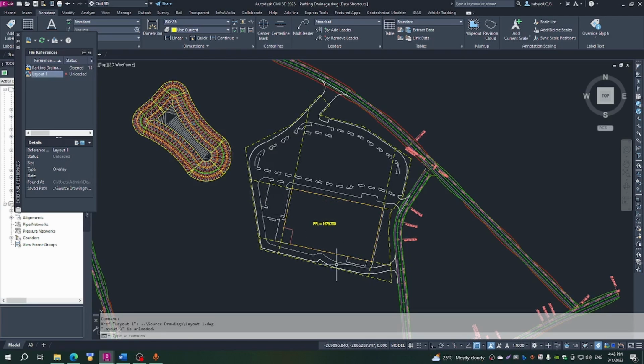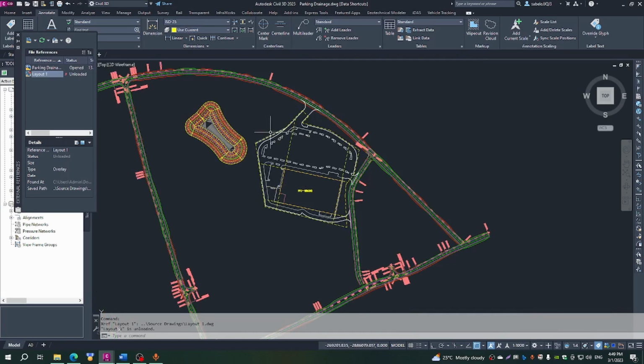When we model a site like this, there is a general drainage pattern we want to use to govern how we model our site. In our case, we know our site is sloping in that direction. As you can see at this point, there is a culvert under that road. So we will drain this site towards that low point there. This pond is going to be used by these areas, these developments that are above here.